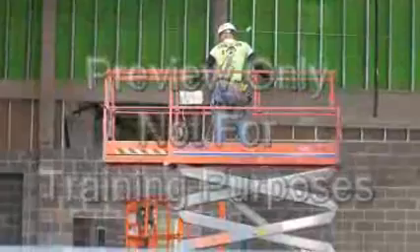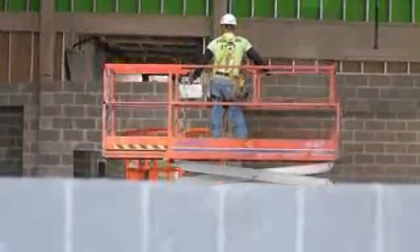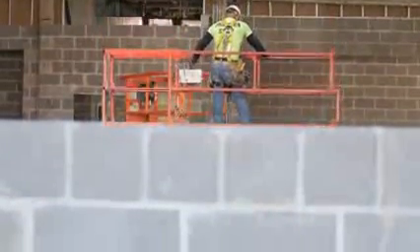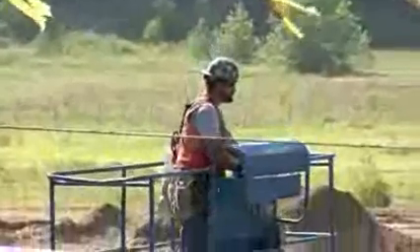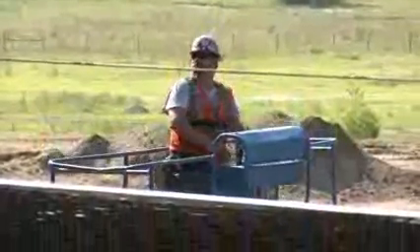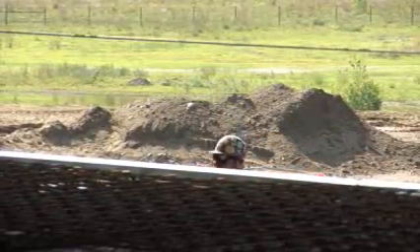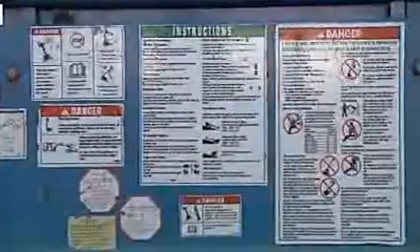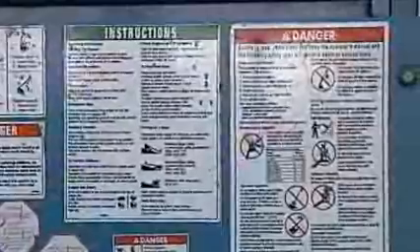Group A, Type 1 and Type 2 MEWPs, such as scissor lifts and manually propelled elevating work platforms, generally do not require the use of secondary fall protection. Group B MEWPs always require the use of either a personal fall arrest or a personal fall restraint system for the operator and occupants. There are many safety rules concerning MEWPs. It is important for employers and operators to know and follow them all.